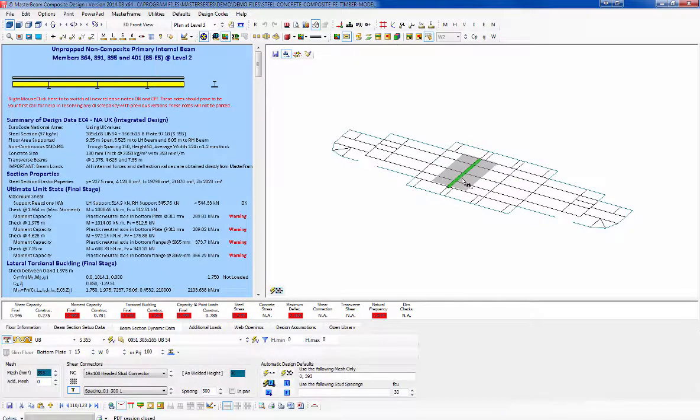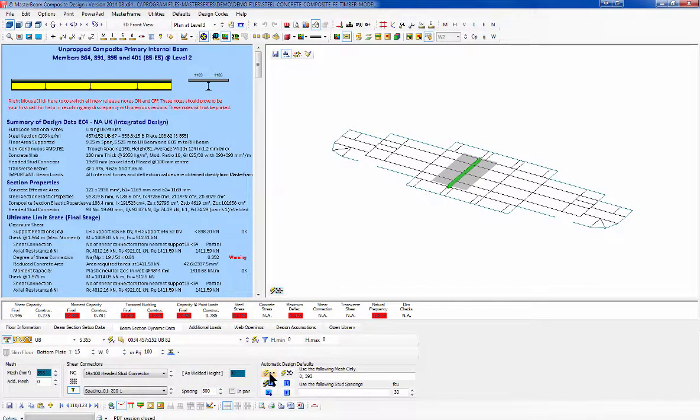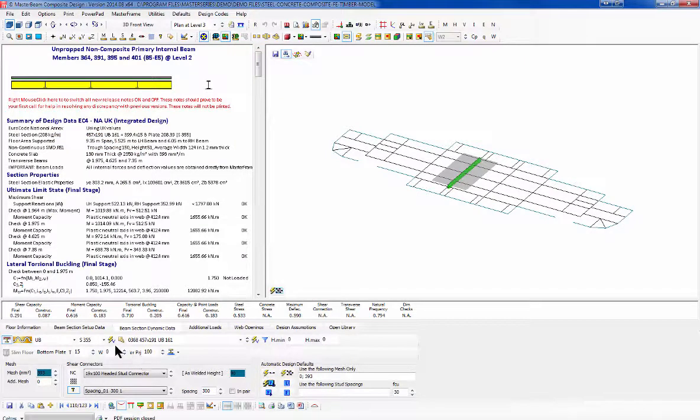On this big beam that we're working with, remember we did this, it is a 305 with a plate. It's probably not going to work. It's well overstressed. I just put that in for demonstration purposes. If you wanted to make that work, we could ask it to try and do that for me, and it's just going to go a wee bit crazy and say that we actually need a 457191, and we probably don't actually need a bottom plate either. And we'll just take the thickness of that out. And it's fine without having to have the plate welded on the bottom.